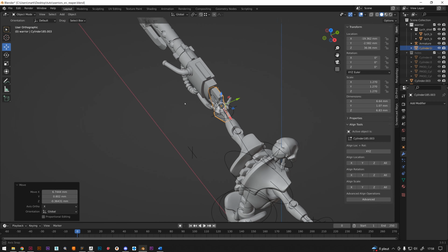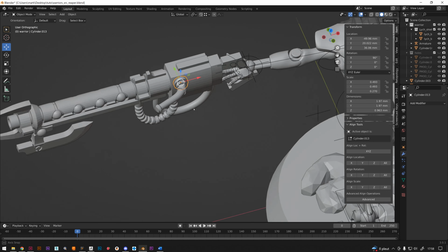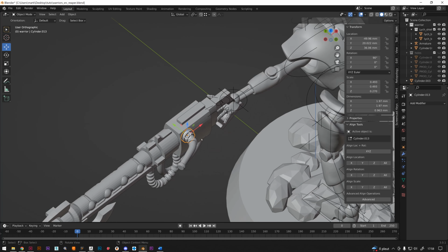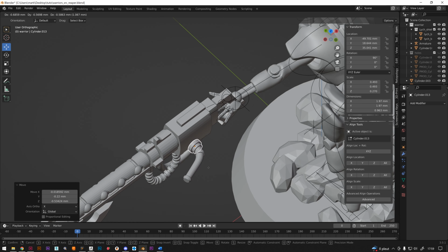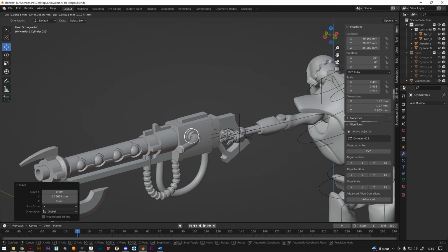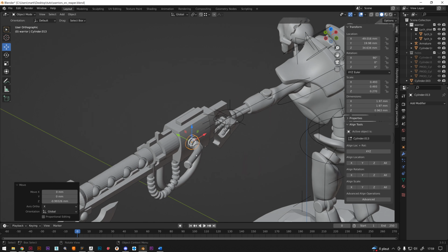But you'll see, this technique using the G key is really nice because, once you press the G key, the object is moving of course, but if you realize that it would be better to use an axis to move that object, well, you just have to press the X key. And now, we use the global orientation of the X axis to move the object, just like if you were using a gizmo. And it works with the Y axis by pressing the Y key, and the Z axis by pressing, guess what? The Z key. Blender shortcuts are really well designed.